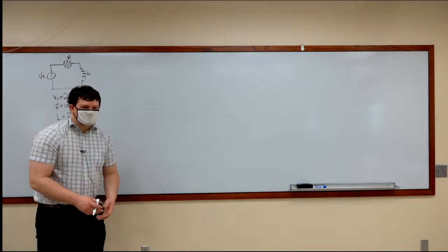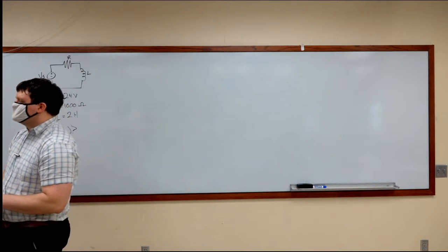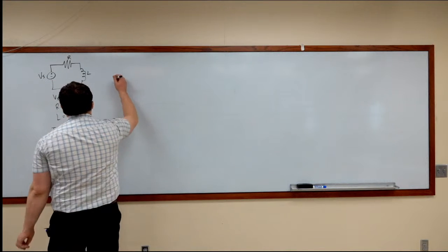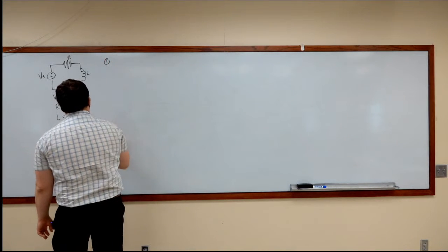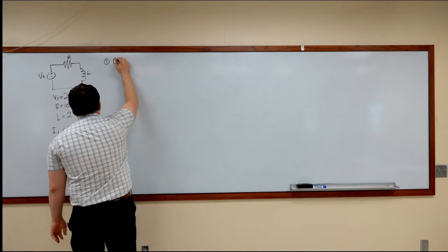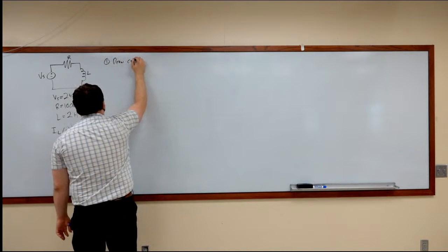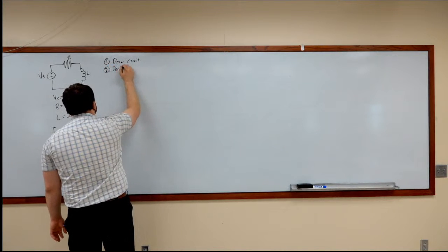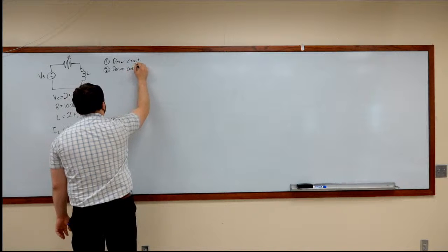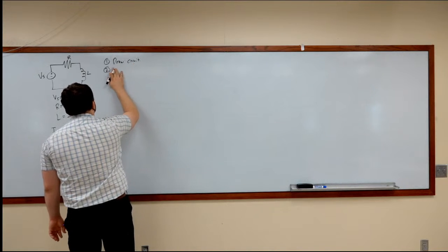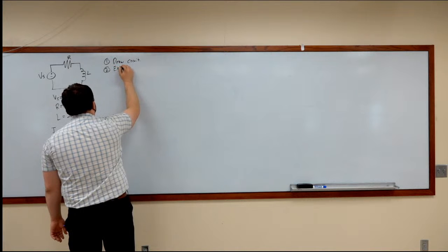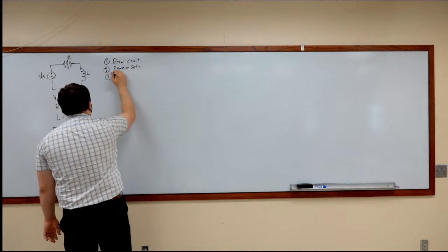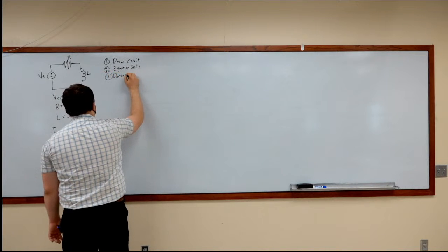Well, the solution method is the same as we did for RC systems, step for step, okay? And I didn't exactly give you those steps correctly the first time, so I'm going to give them to you again. First step, draw your circuit. Second step, get your equation sets. Step 3, this is when you derive your constitutive equation.